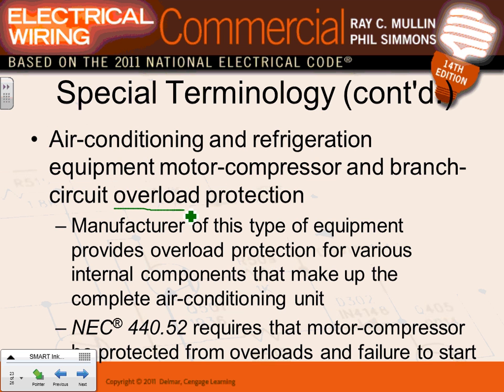Overload protection for compressors and motors, guys, is always provided by the manufacturer. Typically, Joe, my friend, inside the chiller, the overload is set completely as part of your controller. We rarely, if ever, size an overload for a chiller or a compressor. Look at the air conditioning, it all comes in that box. All we provide is power to it and a control circuit, the load and a disconnect. The overload is provided by them.